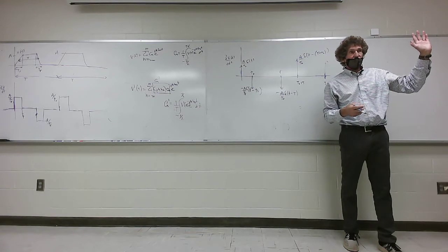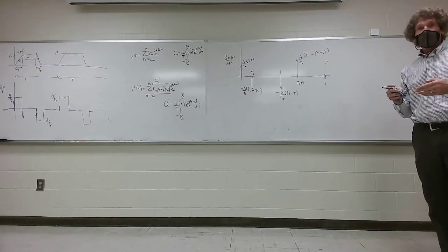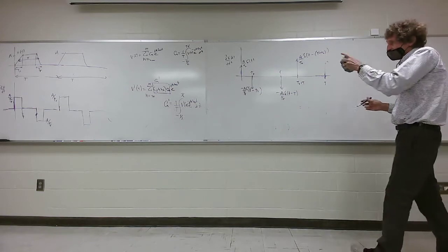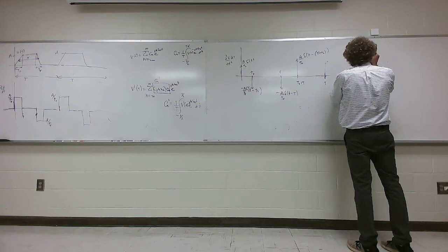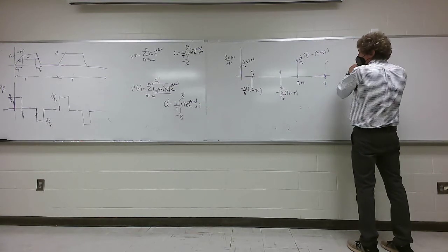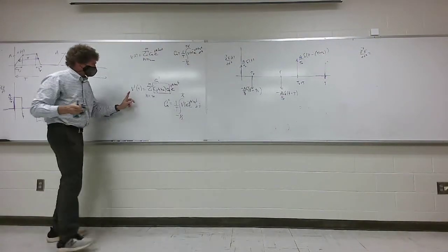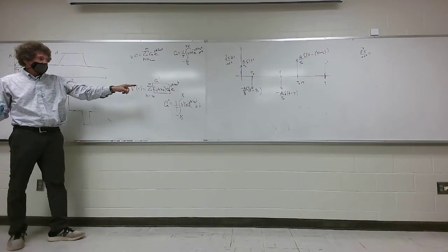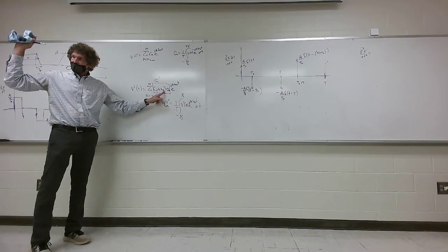Please try to focus. Now, the one thing about this is, that's got to be a Fourier series. Any repetitive function, periodic function, can be expressed as a Fourier series. So that means the second derivative of v with respect to t squared is going to be, and I can take a look at this, here's the first derivative, right? So if I take another derivative with respect to t of that function, you see how I just get another j n omega naught right here? How many see that? With me on this?